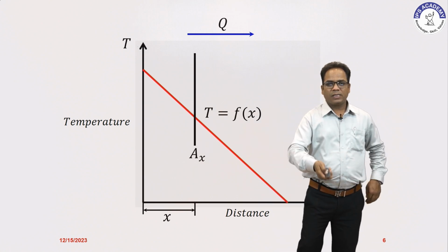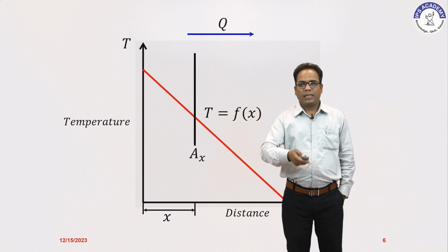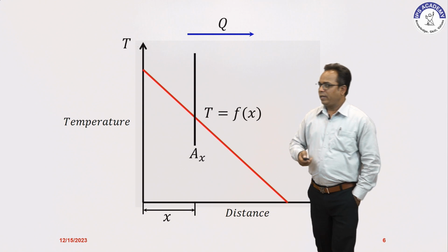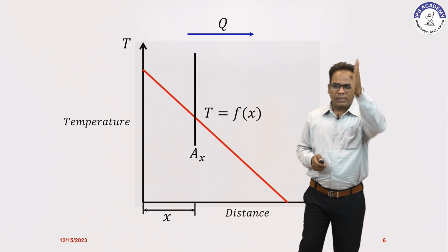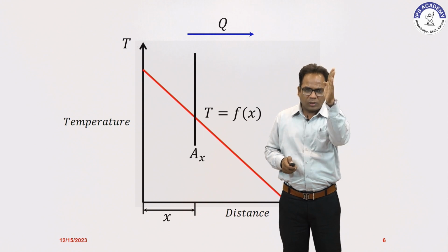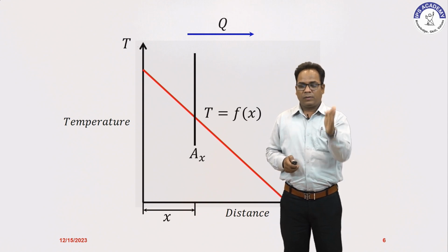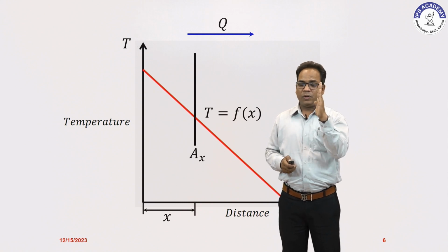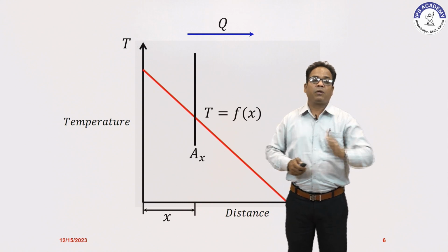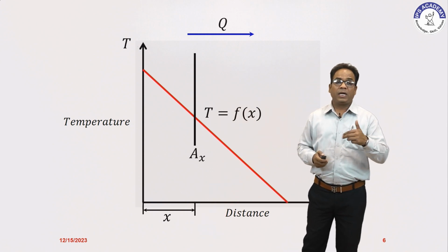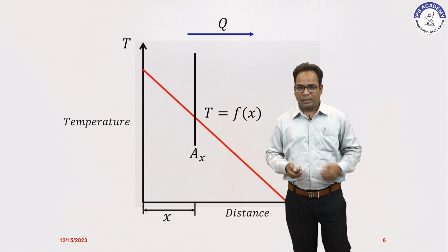So this is the cross-sectional area across which the heat is going to be transferred. Why am I considering this area? Basically, this is the perpendicular, cross-sectional area across which the heat is going to be transferred. The area you consider must be perpendicular to the direction of heat flow. In this way you can identify the amount of heat flux, right?